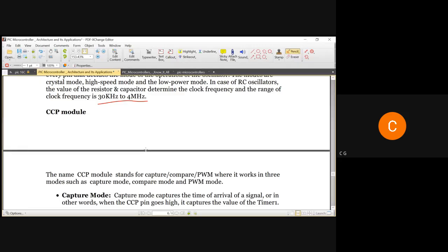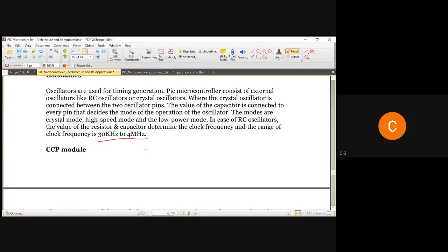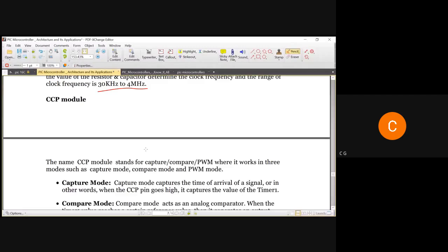People keep a higher frequency configuration, and then using internal programming they apply some sort of mod counters. The role of a mod counter is that it counts the number of pulses. Say a mod 10 counter will count 10 pulses, and then it will generate its own clock signal. Again it will wait for 10 clock pulses to come. In this way you are dividing the clock pulse by 10. So this is one idea.